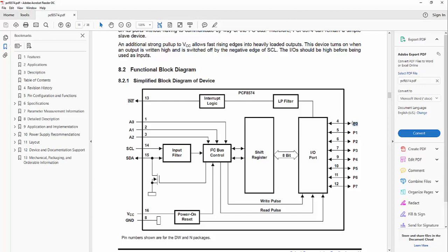This depends on whether I'm connecting the LED with a resistor to VCC, then the light on will be 0, or I connect the LED from resistor to LED and GND, so by positive logic, 1 will light the LED.